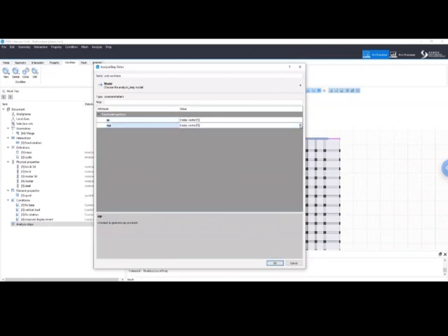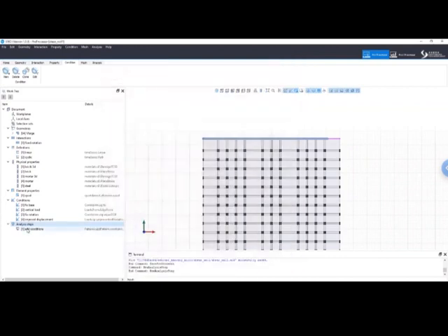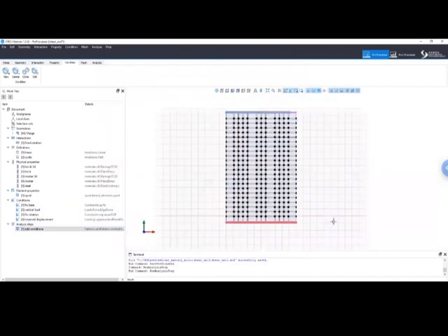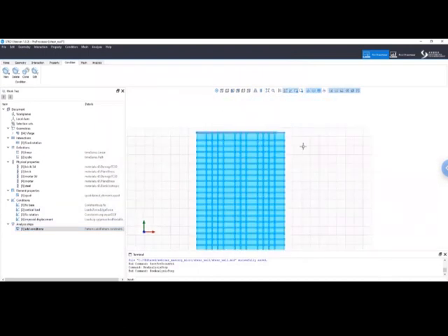And then I go under multi-point constraint, I make room for one, and I choose the fixed rotation. Okay? So we press OK. And OK here. So the first analysis step will apply the fixed base and the kinematic constraint since the very beginning of the model.